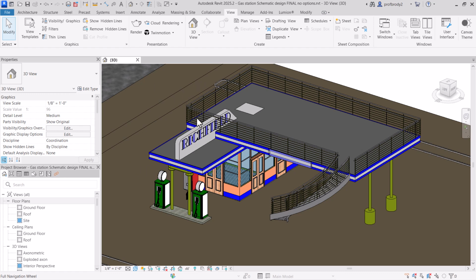Now, other things to consider. I like to close all of my windows except for one when I launch Lumion. And the reason is because when you launch it, it likes to launch from a 3D view, but it can get confused if you have like 100 windows open. As before, make sure the windows aren't in realistic view. You want to try to reduce the amount of load on your computer as much as possible.